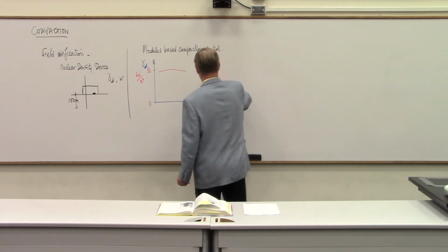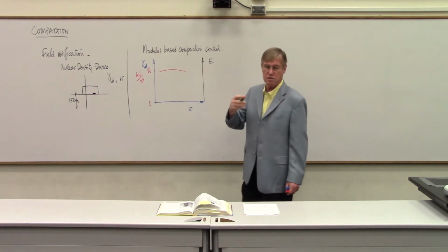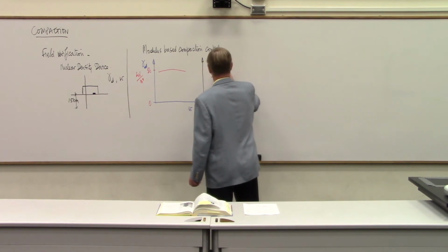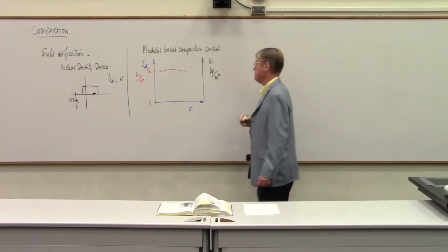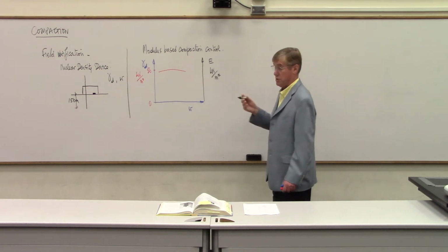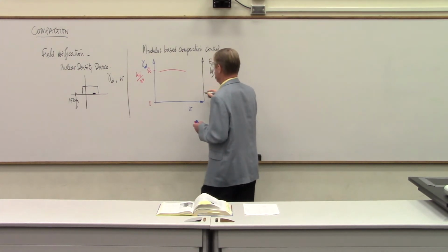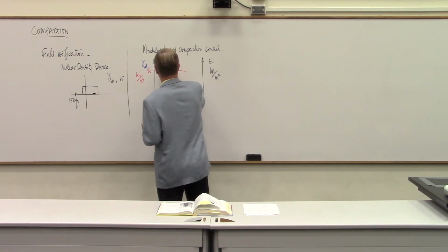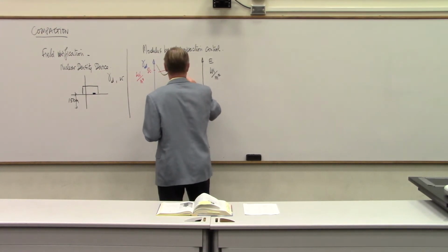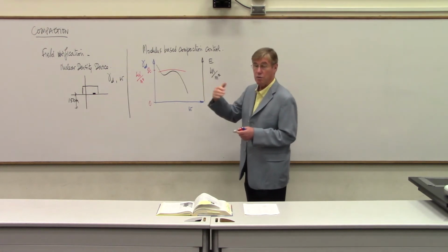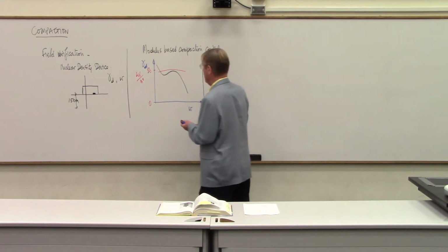If, on the other side, I also plot the modulus. And so the modulus, and we'll come back to modulus and deformation of soil later on in the course, but the modulus would be in kilonewton per square meter. And modulus is a measure of stiffness of the material. If you did that, you would find that the curve is quite a bit different, and the peak may not be the same, but certainly the modulus drops down much more than the density when you're on the wet side of this optimum moisture content.